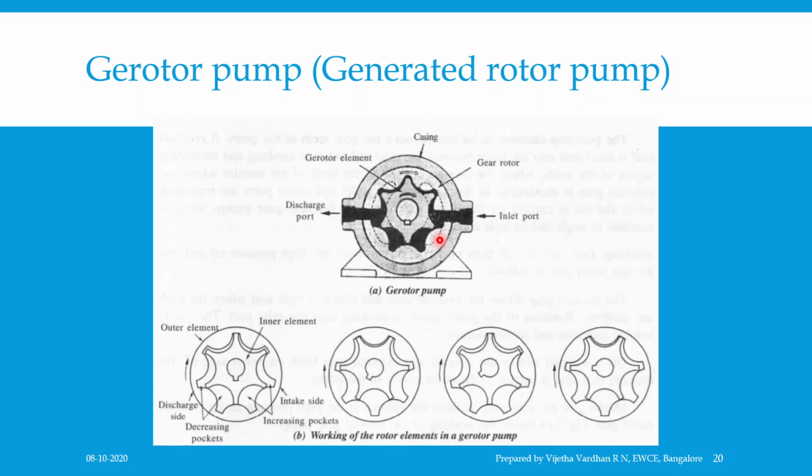The housing and cover plates, that is the pressure plates, are mounted to the designed dimensions. Hence, for a given gear pump, it is not possible to change the elements to different dimensions. Thus, the displacement of the gear pump remains fixed. The only possibility is varying the displacement by varying the speed of the pump.